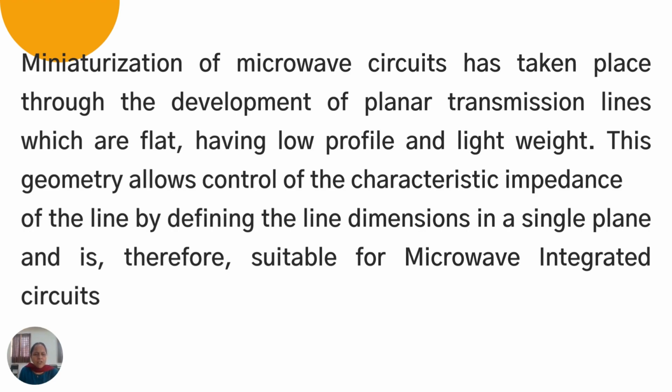Miniaturization of microwave circuits has taken place through the development of planar transmission lines. Since we introduced planar transmission lines, the size of our microwave circuits has been brought down. They are lightweight, low profile, and very small. This geometry allows control of the characteristic impedance of the line by defining the line dimensions in a single plane, and is therefore suitable for microwave integrated circuits.